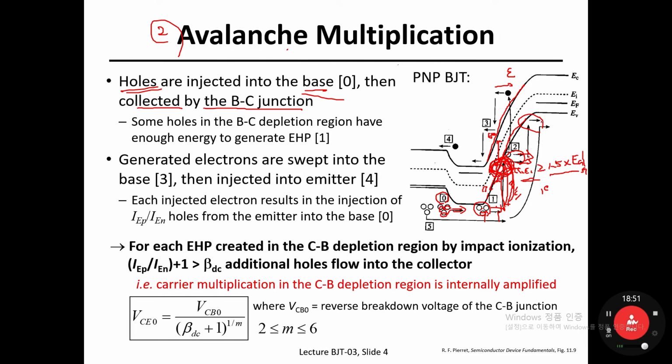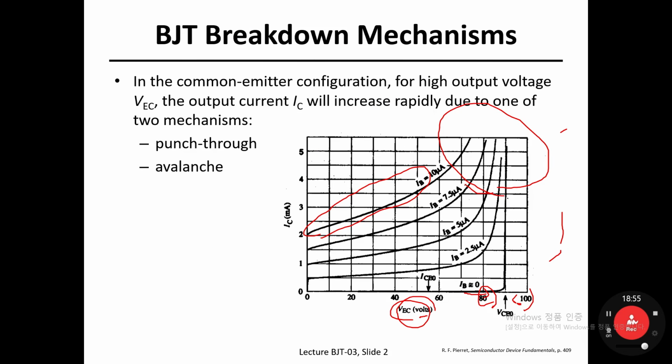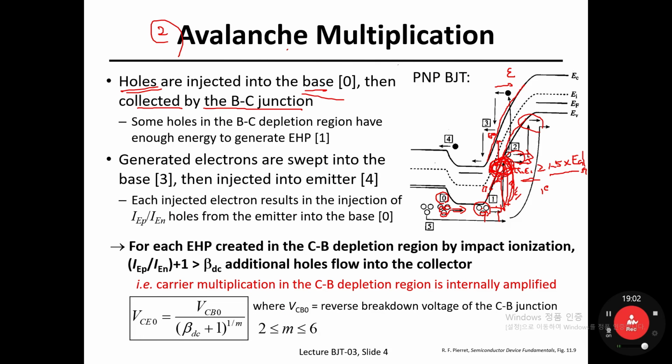How come the avalanche events can happen then? How come in your output characteristic curve, your output current I sub C is exponentially increasing? So internally created electron-hole pairs are the main driving force. How come your exponentially increasing output current can be observed, monitored and measured in your measurement tool? All right. Then I guess I have already explained it here.